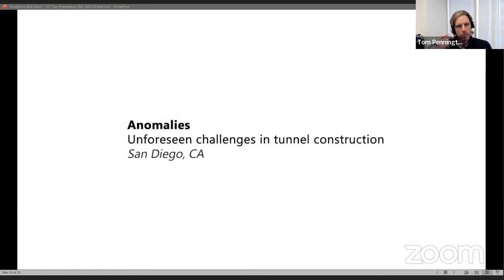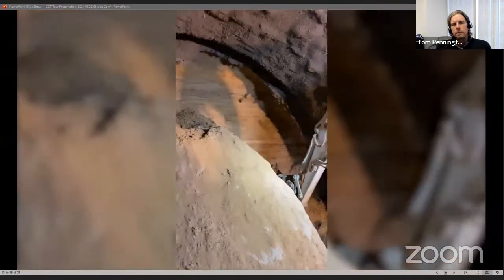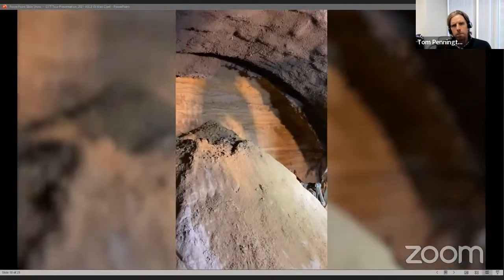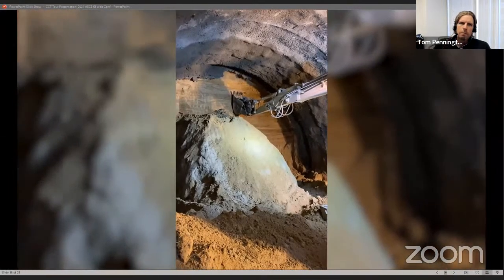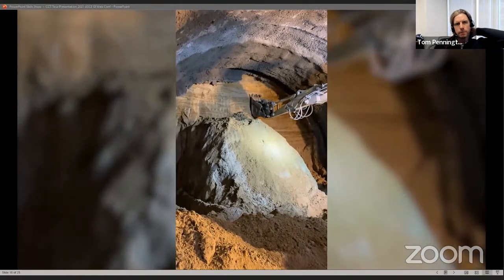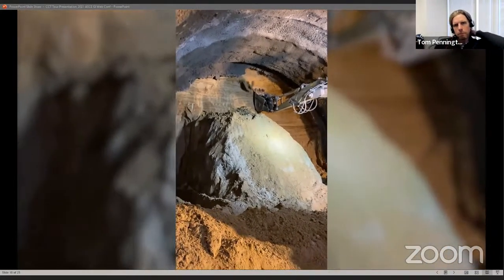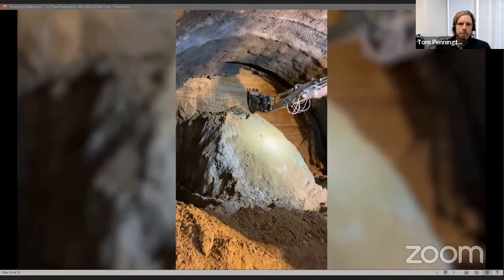To date, there have been 2 notable events that challenged the construction team during tunnel excavation. The first was fast-raveling ground. Unstable ground is an adverse condition for tunnel excavation since unstable ground can progressively extend beyond the limits of the excavation, increasing ground deformations and causing additional settlements at the surface, which may cause damage to buildings or utilities.